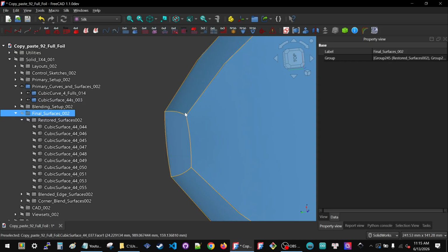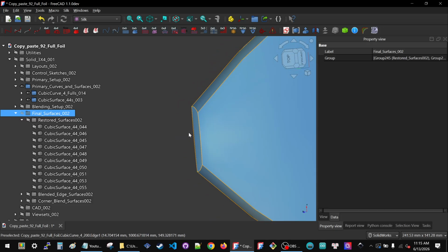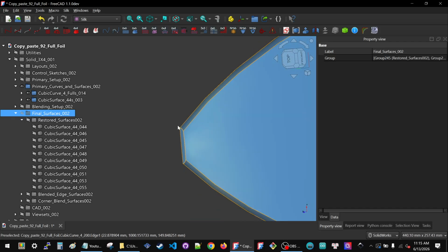So what we did for these edges, making them 3D, we'll do that also. But here we already have sketches. So we already have one sketch, one poly, one curve. We just need to make one more sketch, one more poly, combine and swap. We'll do that for this curve right here. We'll give it some projection in this direction, and we'll do that for this curve on the bottom. We'll give it some projection in this direction. And if we're really, really full of energy, we might even give these guys a 3D version.